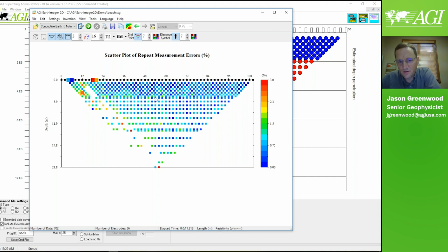Reciprocal also will help show you these point plots with percent error, and you should see just a Gaussian or random error, and less than 10%. But if you see spikes around a connector or other portion of your cable, it indicates there's probably a problem there or something specific about the site. So if you wanted to QC your cables and your system, go out to a known clean site, maybe near the office before you deploy, and just run a quick reciprocal test.